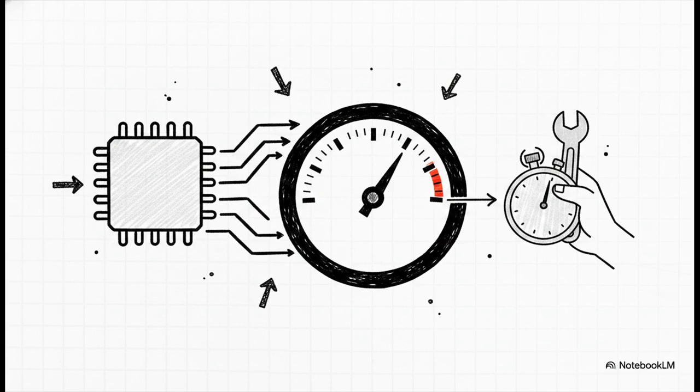We can basically reverse engineer the timing analyzer's calculation. If our constraint was 1 nanosecond and we missed it by negative 0.12 nanoseconds, we just subtract the negative slack from the constraint. 1 minus negative 0.12 equals a real physical delay of 1.12 nanoseconds. That means the absolute maximum usable frequency for this exact adder circuit is 893 megahertz.